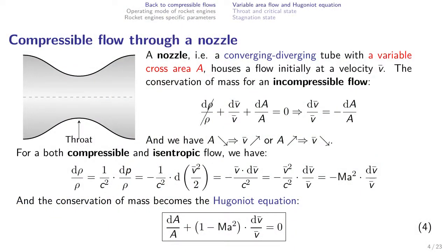If we get back for a few minutes to fluid mechanics, the one based on incompressible flow, we suppose we don't have any variation of density of the gas. We just apply the conservation of mass, exactly the one we defined during the previous lecture, but also exactly the same as the one you previously saw in your fluid mechanics lectures. Because we are not considering any variation of density, the only parameters that vary are the mean speed, the average speed, and the cross-sectional area.